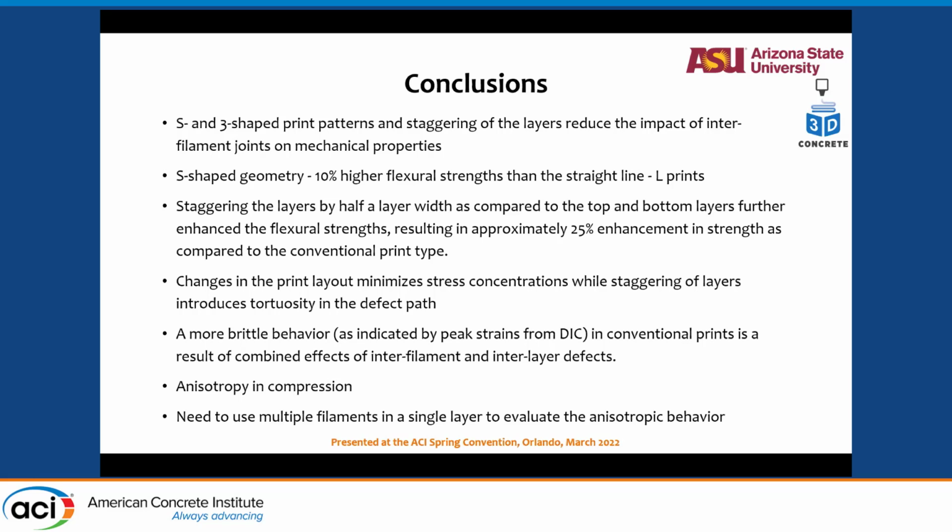You can look at it as a system with a crack running through and through. There is a connection, it is not completely disconnected, but think of a weak joint. So you have bonded 2 different materials, like a repair case. It's not a perfect bond, and you're loading in between. That's why I said it becomes a shear case, not a flexure case, right? So yes, you see that difference if you do that.